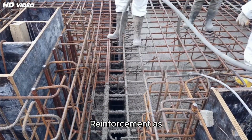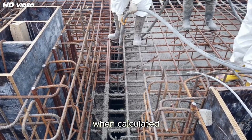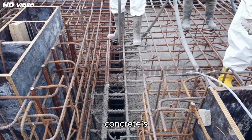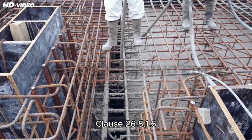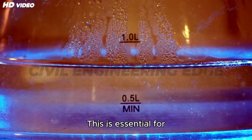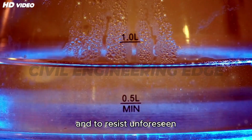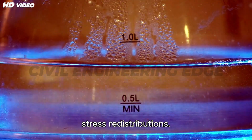Minimum shear reinforcement as per IS code. Even when calculated shear stress is within the concrete's capacity, tau v less than tau c, IS 456:2000, Clause 26.5.1.6 mandates providing minimum shear reinforcement in all RCC beams. This is essential for ductility, crack control, and to resist unforeseen stresses due to shrinkage, creep, or stress redistributions.